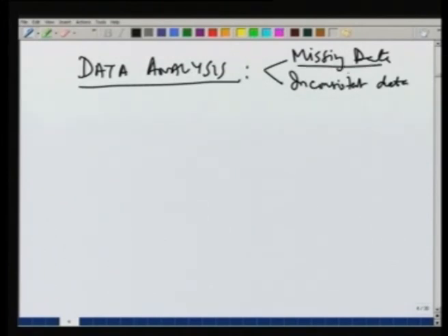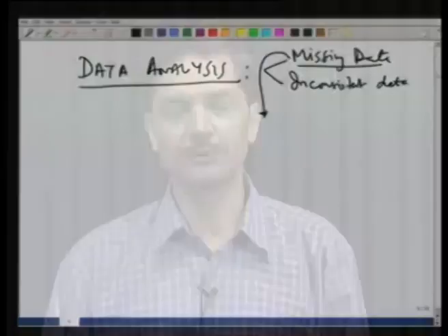Missing data, we saw that there may be various reasons for data being missed, but if there is missing data, we can use the average of nearby rain gauges and assume that the missing data relates to those values. For example, we can take the mean of the values at the corresponding stations, but if the rain gauges have very different normal precipitations, then we can take the average of the precipitation divided by the normal values. Inconsistent data,